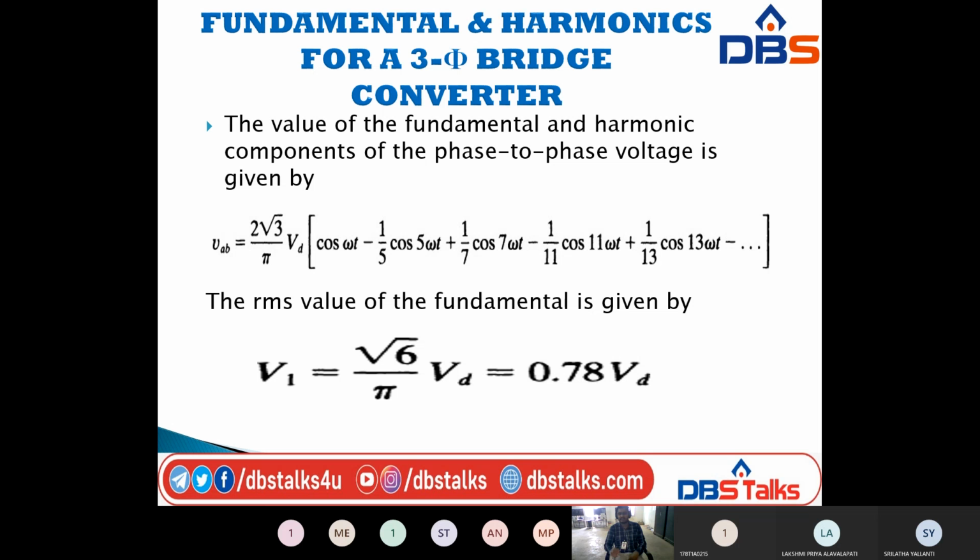So here the RMS value of the fundamental is given by V1 is equal to root 6 by pi VD, that is equal to 0.78 VD. This is the RMS value of the fundamental. Okay.